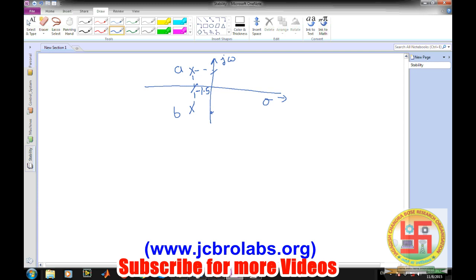Now it's good, but the question arises when our system becomes a little complex, for example a complex system. In order to find the stability of the system, if we look at it carefully, we don't need to find exactly where our roots are lying. We are only interested in whether they are lying on the j omega axis, on the left side of the S-plane, or on the right side of the S-plane.